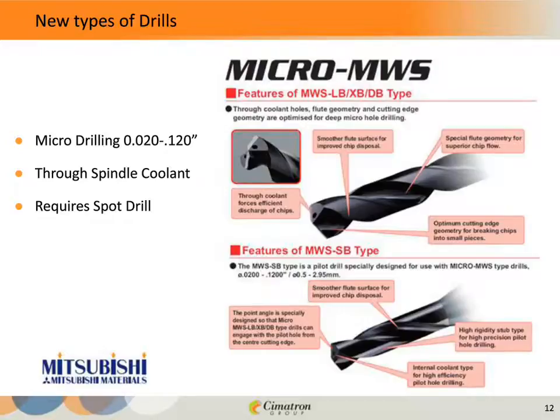And the other thing that I've found out in my research is that, and again, I'm going to speak in generalities, I know that there is not always a black and white when it comes to some of these applications, but generally speaking, if you're going to be drilling with a drill that's under 100 thousandths, probably you should be considering using a spot drill. And then I think over 1/8 of an inch, depending on what length the drill is, probably maybe you don't need a spot drill. But again, I highly recommend you consult your tooling vendor. But I'm going to show you some differences here on the next page.